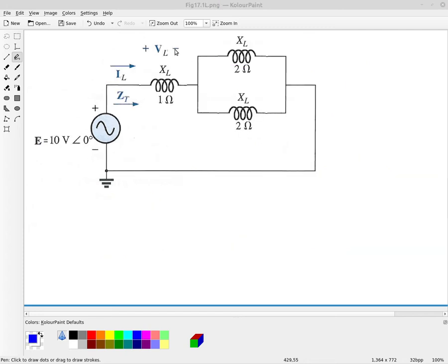Now we have the exact same AC circuit, only our resistors are now inductors. So we have 3 inductors in the same series-parallel type of circuit, with the same values. But these are inductors, so what they're giving us here is the inductive reactance. Remember, there's really a j phase angle with each one of these. They don't show us that in the book. They just say we can tell it's an inductor by the electrical symbol. So we know there's going to be a j term here.